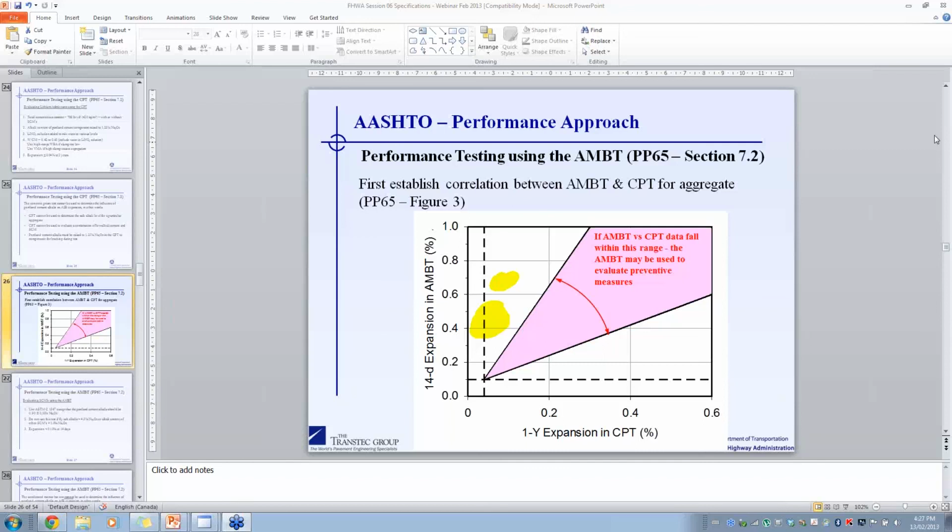So ASR has occurred in fly ash concrete. We can make it occur in the laboratory. However, fly ash can be used to control ASR provided it's used in sufficient quantity. That's really my only comment to the question as it's posed.